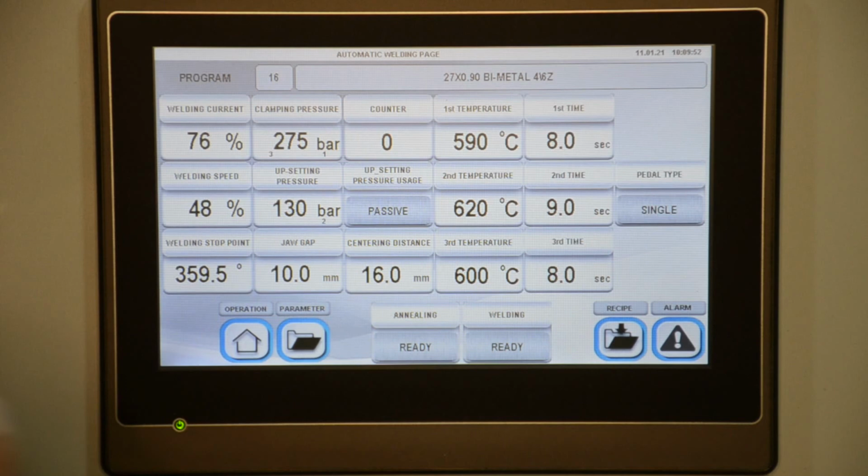There were many questions about when to service or replace the jaws with new ones. On this machine, there is an adjustable counter that will count your operations and it will give you a warning in case it reaches the adjusted value. After you service the jaws, you can click the reset button to start counting from the beginning.